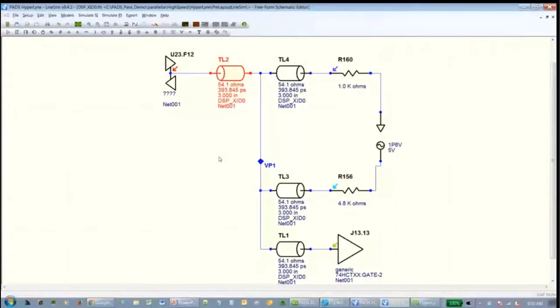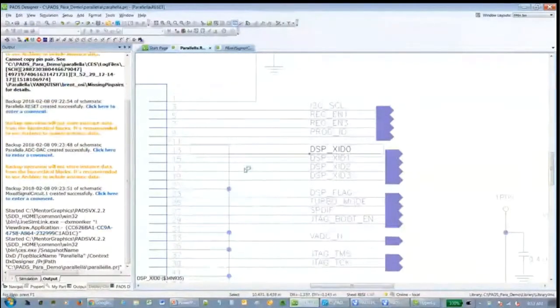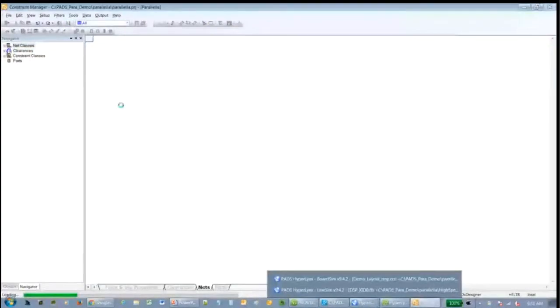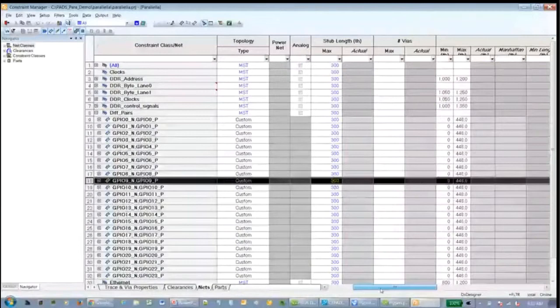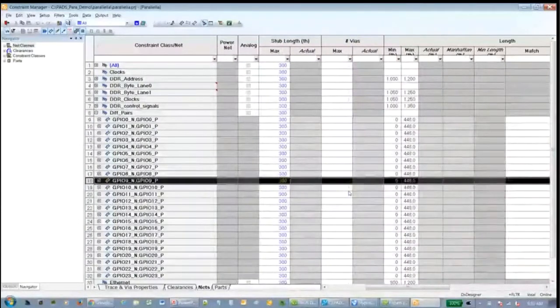Okay. So again, from our schematic tool, I can go into our design rule environment, and I can take those rules that I've defined via simulation if I want to, and I can come in here and set up my nets and classes. I can add virtual pins, max number of pins. I can put length matching information, all at the schematic level, so that when we get into the PCB space, everything's ready to go, and I don't have to play guesswork or produce the design and have to do a prototype in order to check my critical signals in my design.